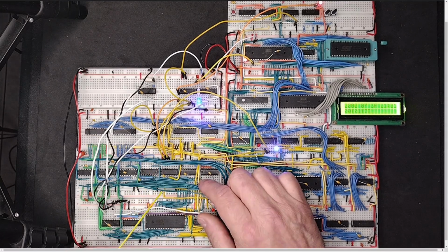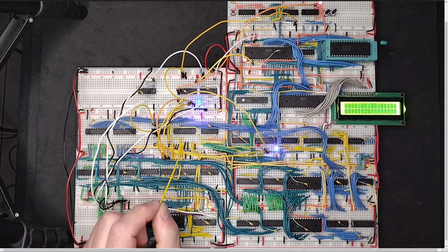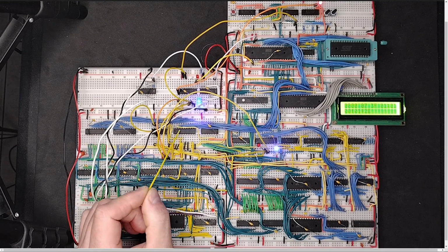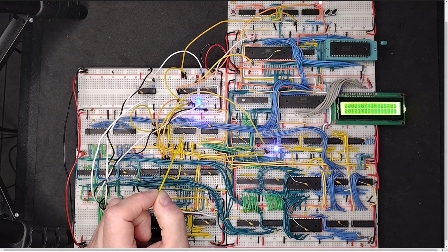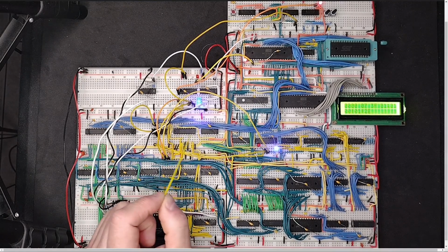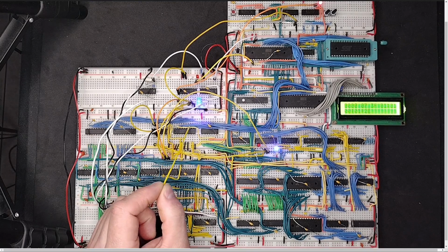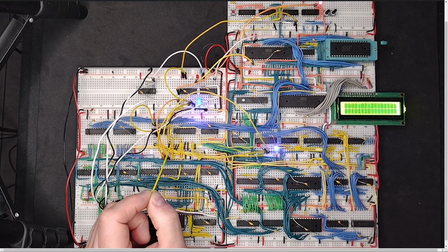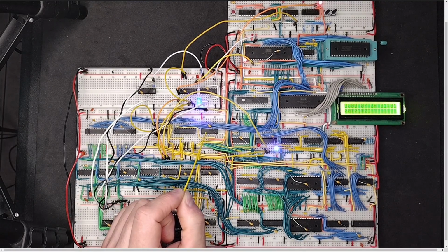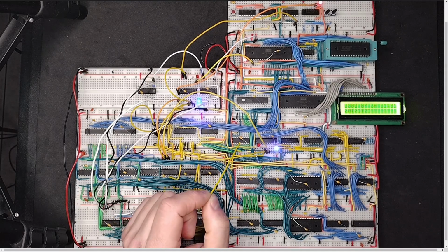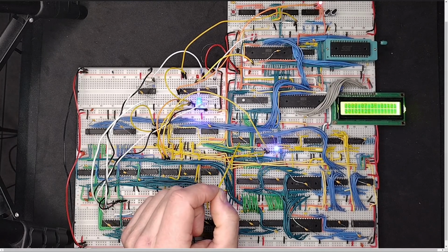So that's the latch, and the output of that latch I run up here to this. This chip is an SN74HCT245 transceiver chip. And this is basically all you need along with the address decoder. This is all you need for a read register. So this is my read register. It's wired to this address decoder. This is just a 74HCT138 address decoder like I've been using. But I wired this exactly like this one, which is for my write register.